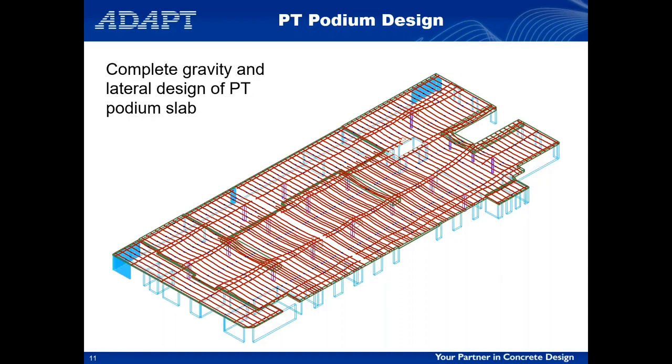So one thing you may want to consider and review in your design approach in your office is, because these podiums tend to be closer to the ground and very close to, obviously connected to, the foundation, you may choose to switch the default boundary condition when you're doing the PT podium design in Floor Pro to fixed as opposed to the rigid roller. That's just one piece of advice to think about, and you can do a quick comparison: take one of your models, run the two, and see what happens.